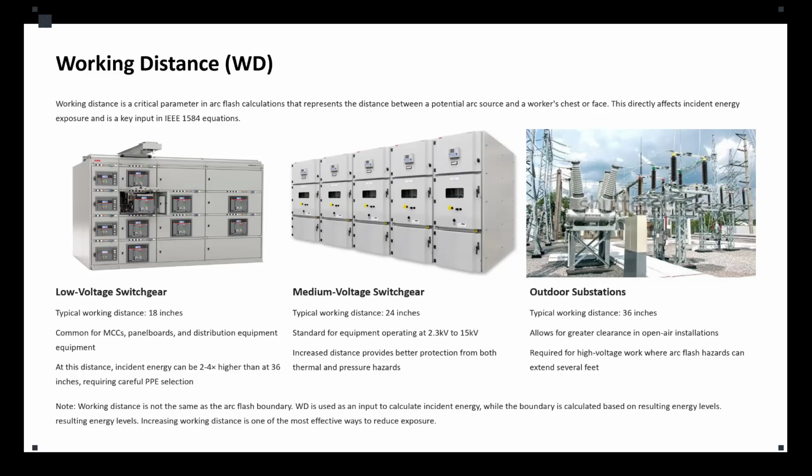Now, there are some standard working distances by equipment type, which IEEE 1584 provides based on the equipment being assessed. Let's break it down by voltage class. We have low voltage switchgears, which is 600 volts and below.